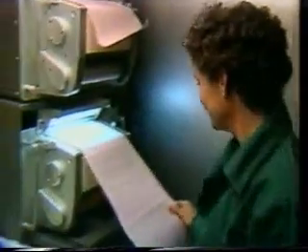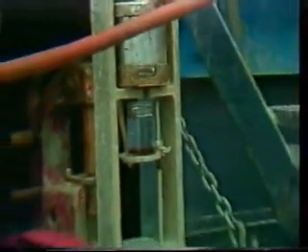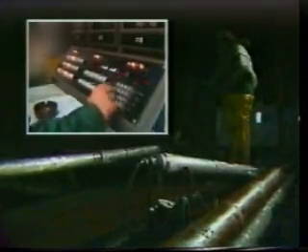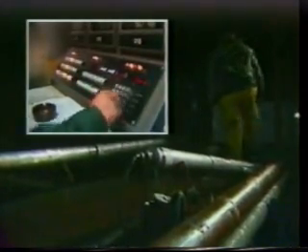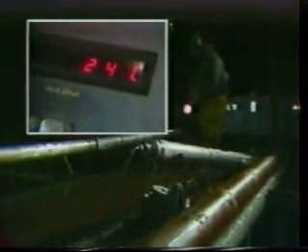As shown here, rigging up includes laying out the logging tools, testing the cable head and cable, testing the logging tools, checking out the surface equipment, and making routine checks of mud properties. As logging devices are assembled together and the string of tools is made fully operational, a before-survey calibration check is made. This confirms that any changes in tool responses from the shop calibrations are within allowable limits or can be explained.